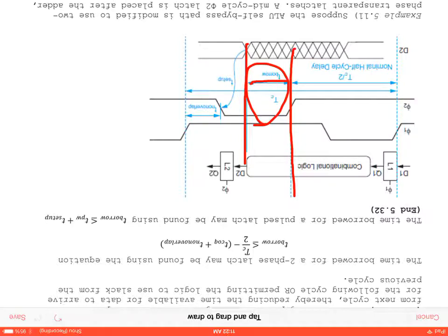We're just burning time. And here, once it goes to 0, we switch to the second phi, right? So therefore, we're moving on. So we can't borrow this time. And this setup time is the amount of setup time we need to be able to properly propagate the token. So we can't borrow this time either.